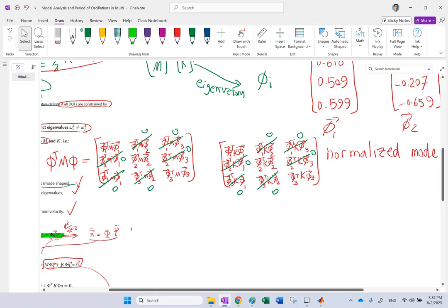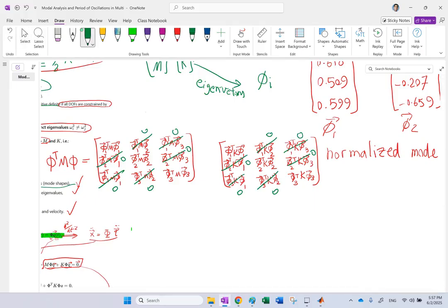Yeah, remember that your M inverse K matrix, the eigenvalues of that were these omega squareds. So this was omega 1 squared, and then omega 2 squared, and omega 3 squared, all off-diagonals 0. That was the lambda matrix. So you might say, well, what about here? What can you do here?